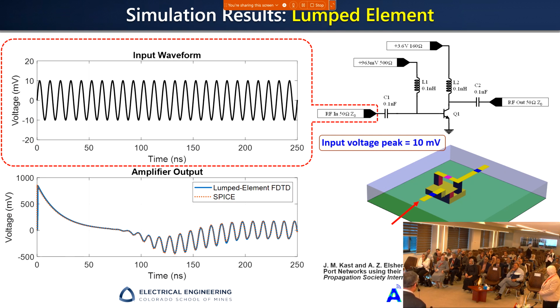So you can look at the noise at those small signals that are going to go into the system. And for this, we need to have the small signal representation of the X parameter. But at that time, in this confirmation, I'm only using a large signal component of the X parameter. Okay?